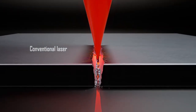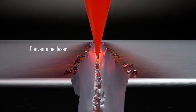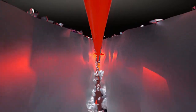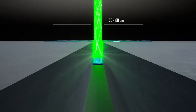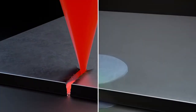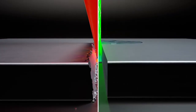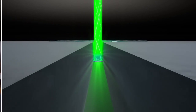Gas assisted laser cutting has exhausted its ability to keep up with the growing demand of quality. They cause thermal damage and contamination on the material. Instead of gas, the laser beam is guided by a thin water jet. Thanks to the total internal reflection, this results in perfect cutting without any damage to the material. It not only offers exceptionally precise cutting, it also ensures the material stays cool and clean.